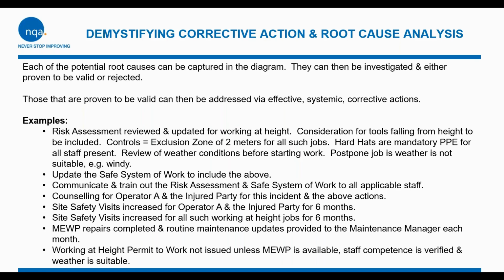So each of the potential root causes can be captured in the diagram. You can then investigate them and prove them to be valid or invalid. So you can just pile them all in there. Those that are proven to be valid can then be addressed via effective systemic corrective actions.